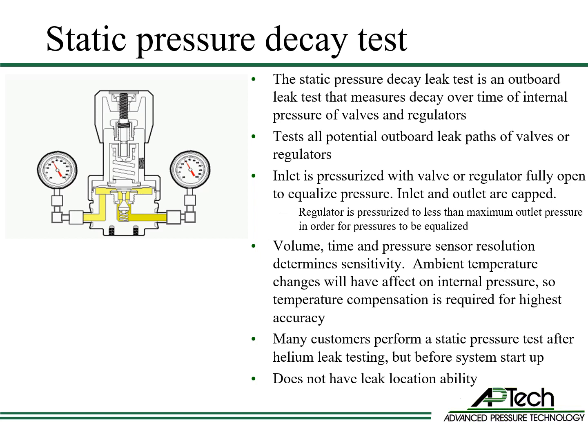Temperature changes from start and finish of test will impact test accuracy, so temperature measurement and compensation is required. Many customers perform a static pressure test after helium leak testing, but before system startup. This method does not have the ability to locate leaks.